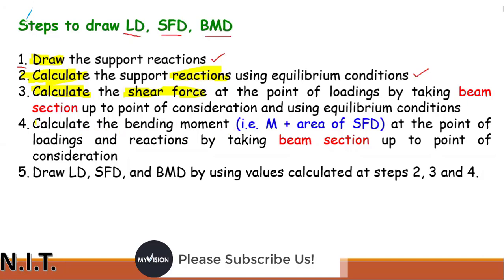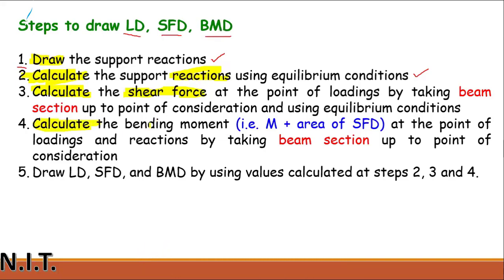You need to calculate the bending moment, and the bending moment can be calculated as the area of the shear force diagram. Simple. Then we can draw the load diagram, shear force diagram, and bending moment diagram by using the values which are calculated in step number 2, step number 3, and step number 4.